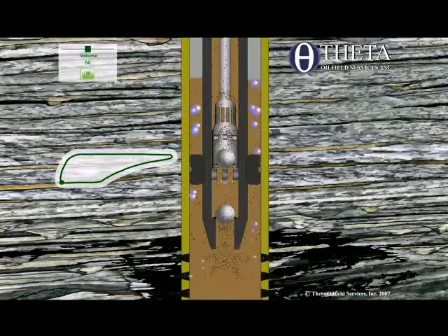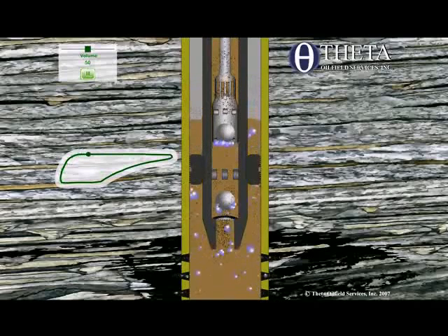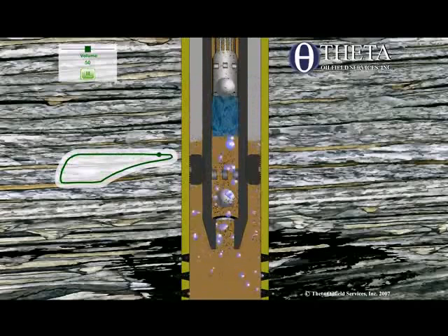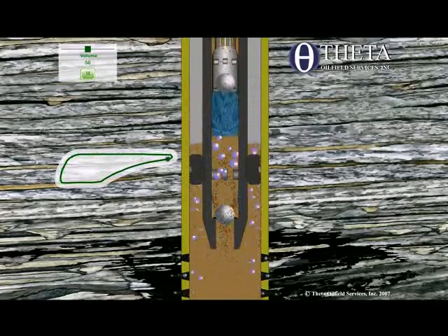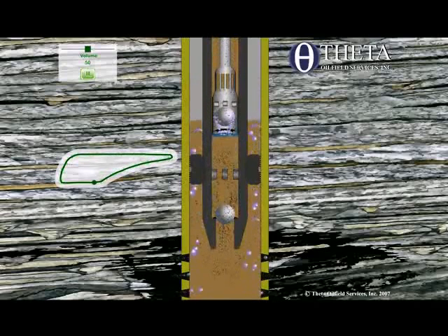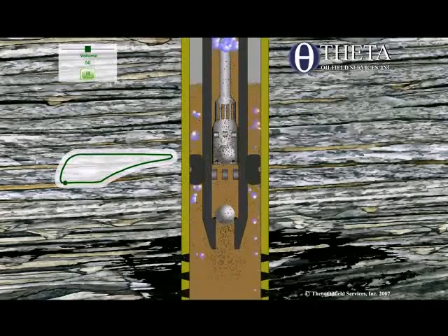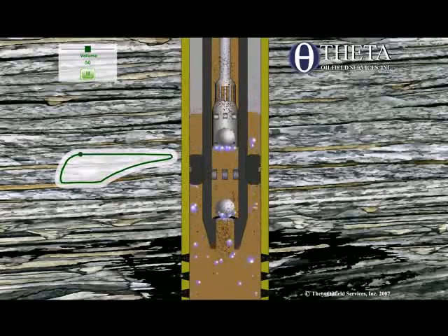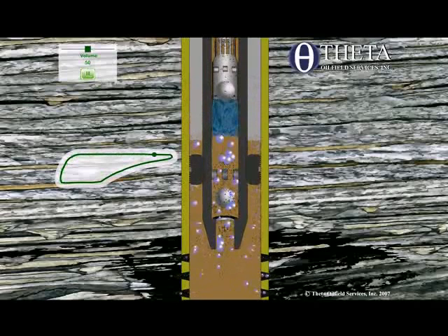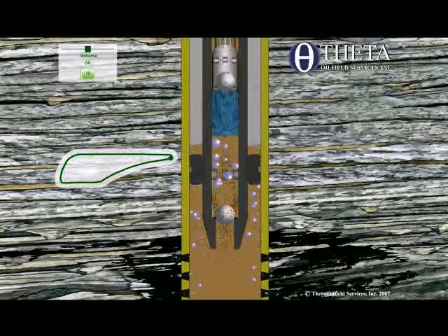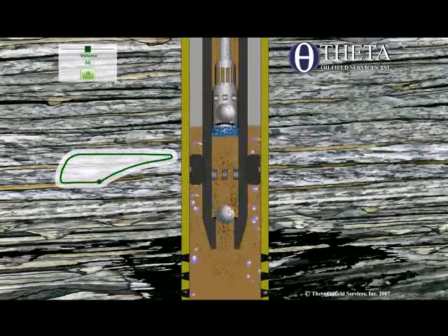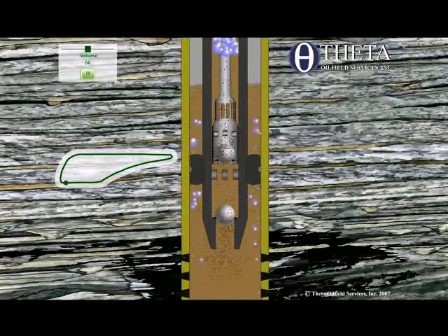You know, at the beginning of the upstroke, you're expanding the gas over here. This is the gas expansion part. Both valves are still closed. And then finally, when you expand the gas enough to open the traveling valve and pick up the fluid load, then you have a constant load for the rest of the upstroke. And then on the downstroke, you have to compress the gas in the pump before the traveling valve can open.